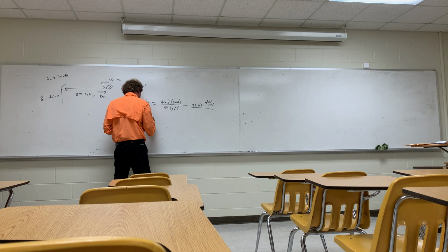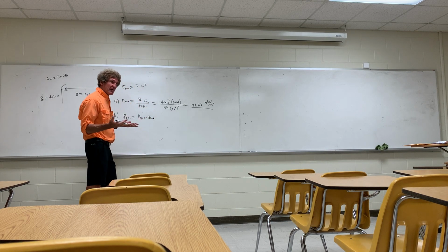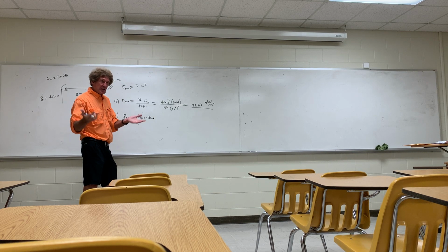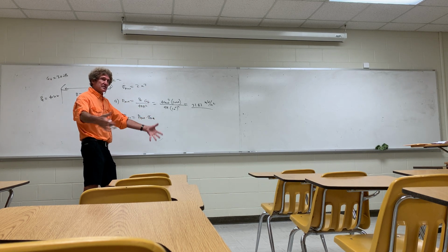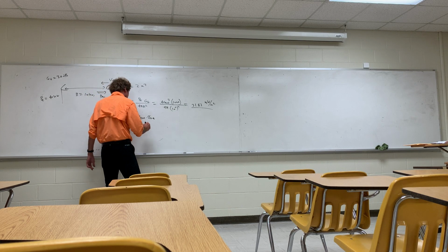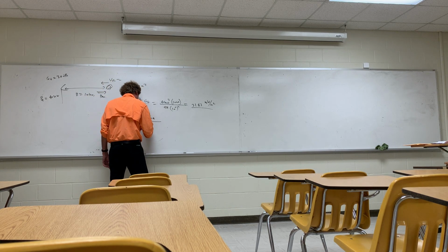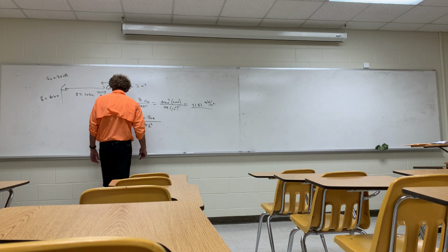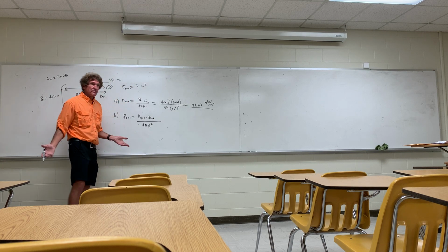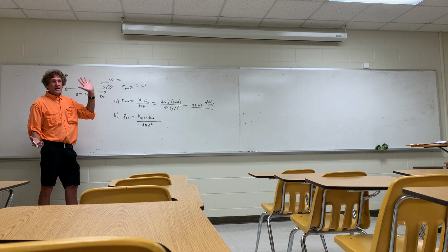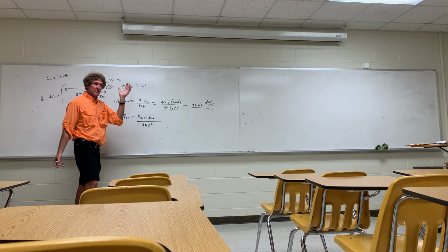Then I multiply it by the radar cross section. Now that's the total scattered power. Then I divide that by 4 pi r squared, because now that's spreading out isotropically. So divide by 4 pi r squared. Now I've got the power density back at that radar, right? Finally, I have to get the area, the electrical area that catches it. Think of it as a catcher's net. That's how I always do this.